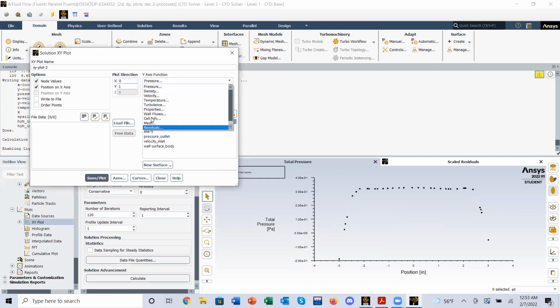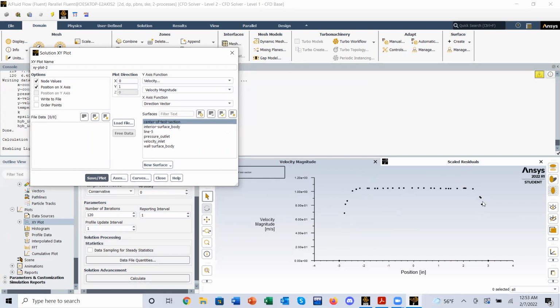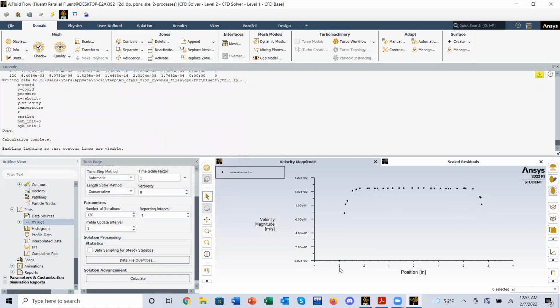And then of course, you can look at your velocity plot, and that should be similar to your dynamic pressure plot because when you're near the bottom of the test section vertically, then it's going to be lower because it has the wall. And near the top, same thing, it's hitting the wall, so it's going to be lower as it gets there. And then the center is going to be almost equal because the velocity is coming in streamlined. That should be it for that.